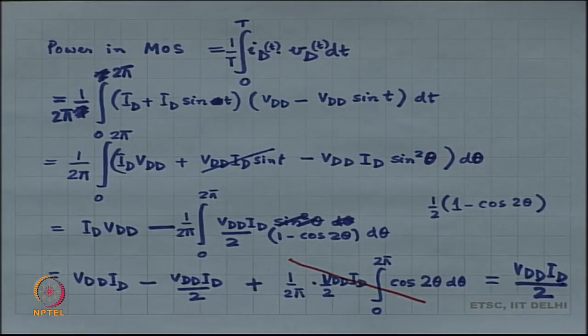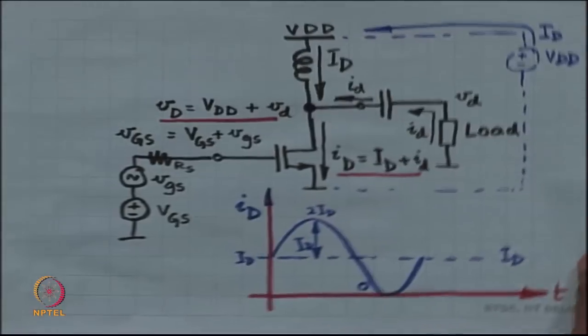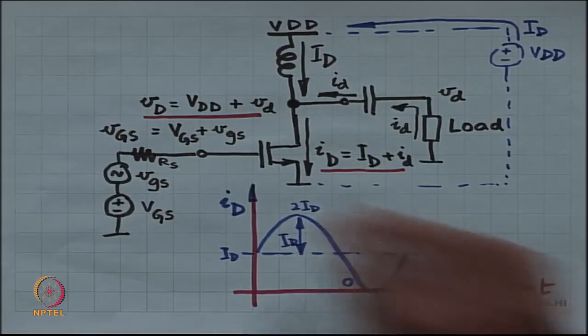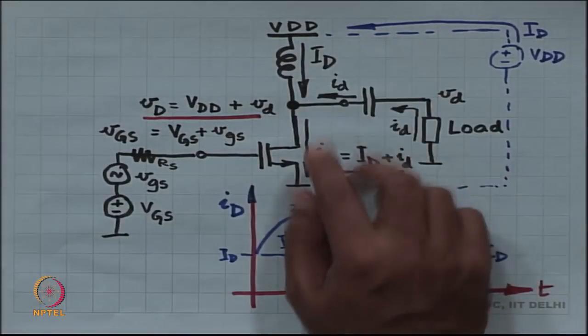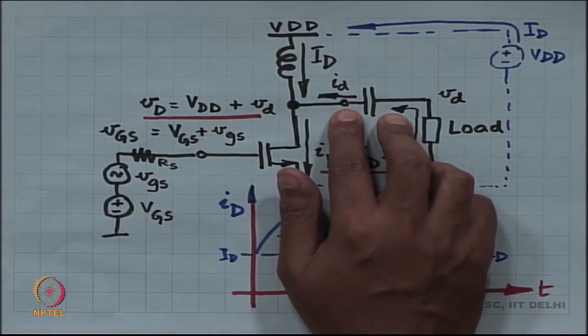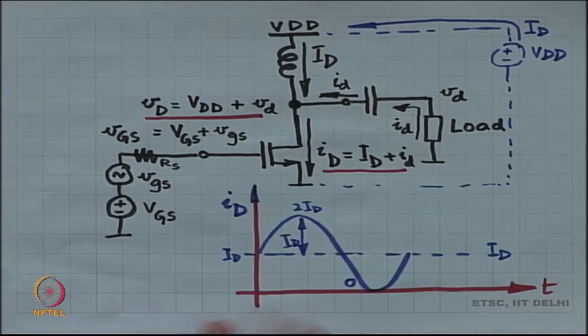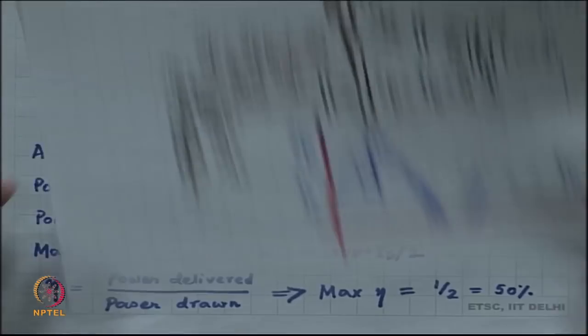So, there, that is how you actually do it. Okay. So, what did we figure out? We figured out all of the following. We had the simplest of all circuits, common source amplifier, right. Biasing was done with the help of an inductor, capacitor was used to decouple the DC operating point from the load. Fine. Input was applied on one side.